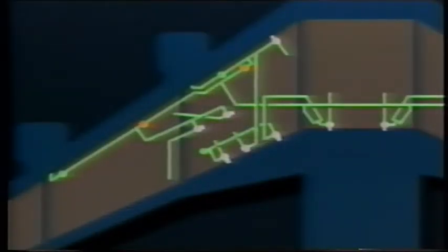Four cross-feed valves are mounted in the cross-feed manifold and control the flow of fuel from the tanks to the engines. Four fuel shutoff valves, commonly called spar valves, are mounted through the front spar. They control the flow of fuel to each engine.